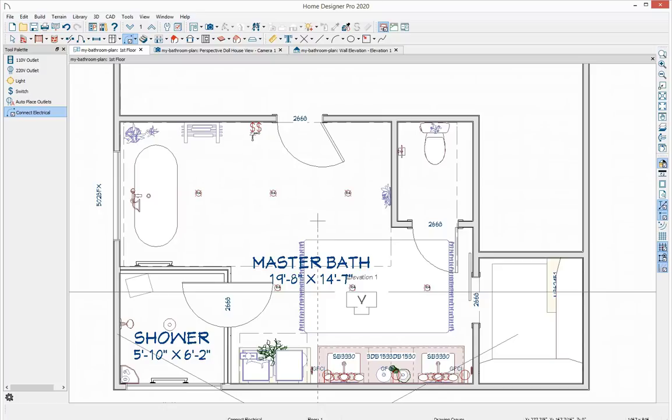That lets you know when you have something that you can connect to, and then you just click and drag to the light elements that you want to show for your electrical plan. And you can also further edit how these display just by using the edit handles with these lines. And you would just continue this process for the other parts of your plan as well to finish off your electrical.